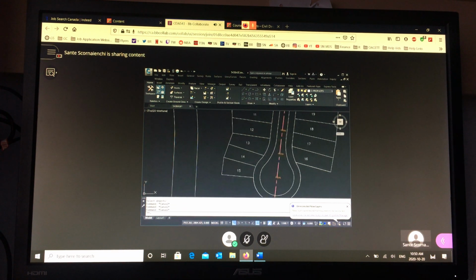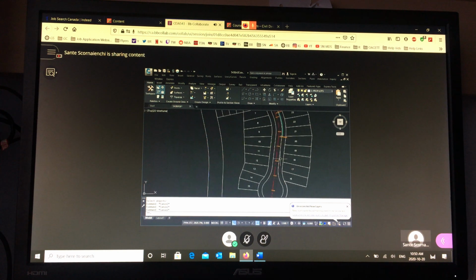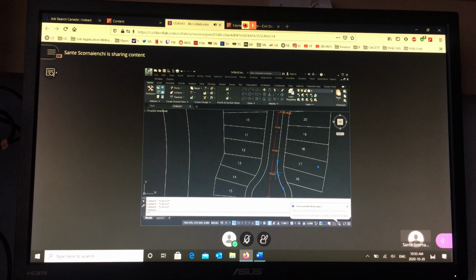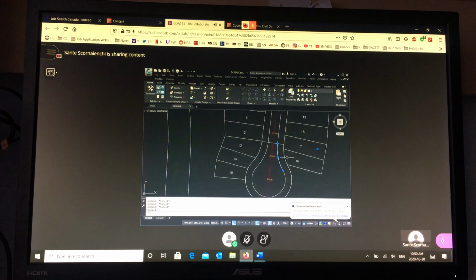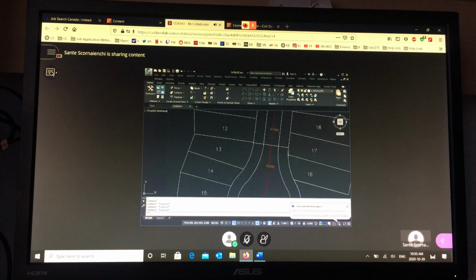Okay, so remember the last time we have a standard 20-meter right-of-way is where the widening starts, right? So right here, these two dots, that's the last time. So I'm going to draw that in from here to here. So, you know, along here, all the way to this point here, we have a standard 20-meter right-of-way. Then there's where it changes. So I want to create an alignment along the gutter line that goes all the way around and back again. That's the unusual, non-standard part of this.